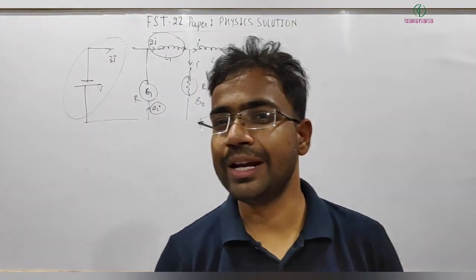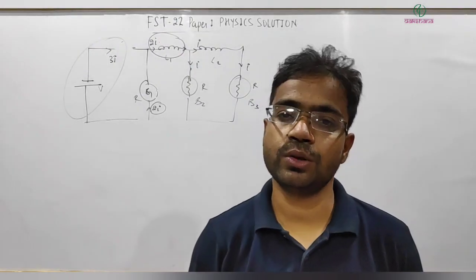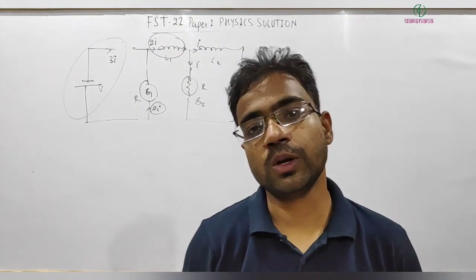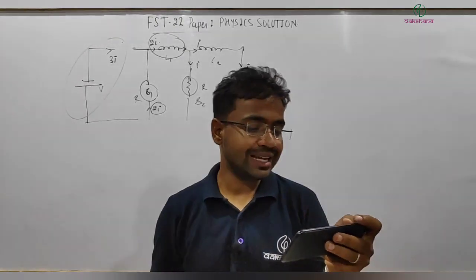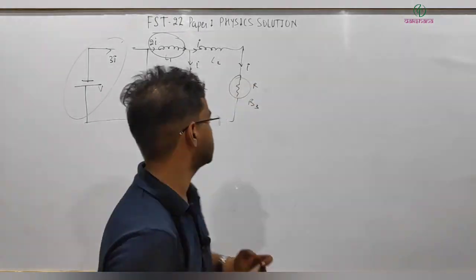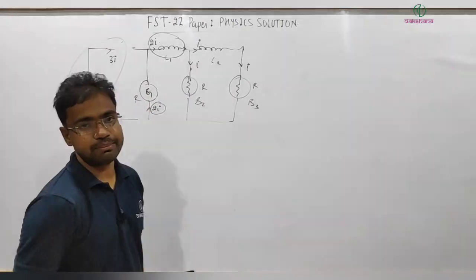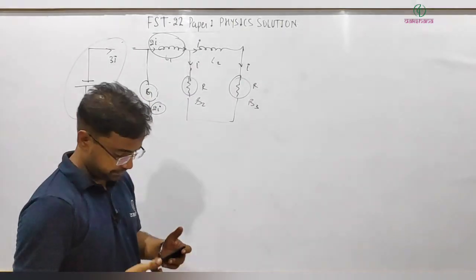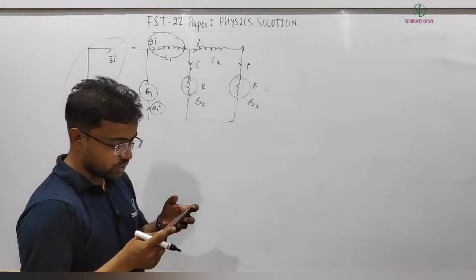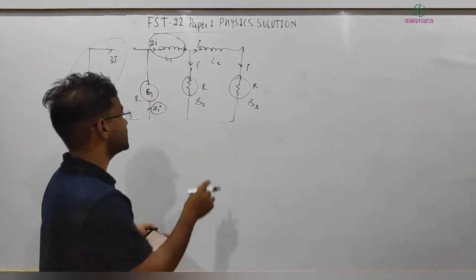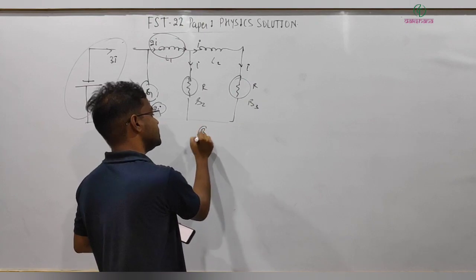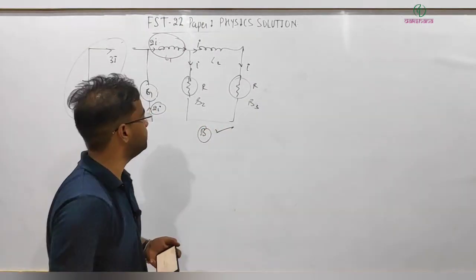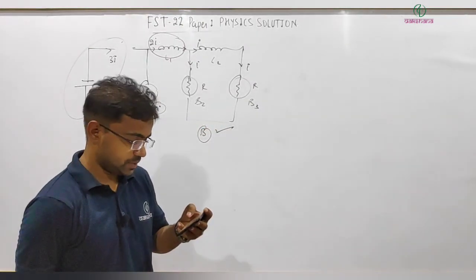So you must be clear now that if higher current is flowing through any bulb, it must be glowing even brighter. So now we can answer easily. All the lamps are turned off? Definitely not, because current will be there in each lamp and they will be continuously glowing. So brightness of B2 and B3 remains unchanged because current remains unchanged. In these two it is not changing, so statement B is correct. Brightness of bulb B2 and B3 will not change.